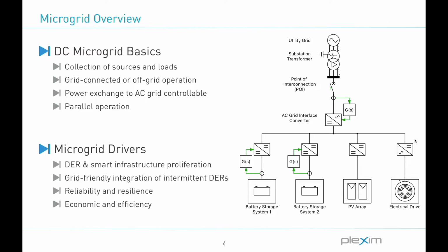usually what we have if we want to connect such a system to an AC grid, we have a double conversion converter. So we have an AC to DC, then a DC to AC conversion stage. And if we connect our variable speed drive directly to a system that is based on DC, we can omit this first conversion stage and increase the efficiency of our system. And for sure, at the same time, also reduce the costs. So there are quite a few arguments for a microgrid based on DC technology or for microgrids in general.